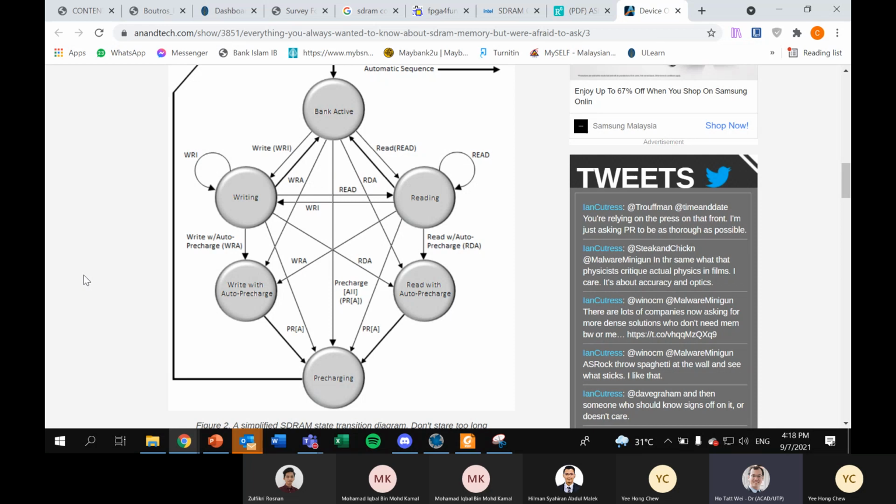You don't need to implement single read, or single read followed by write, or read followed by read. Just do burst read followed by pre-charge, and burst write followed by pre-charge. You just pick one burst number. You don't need to do all the other burst numbers.